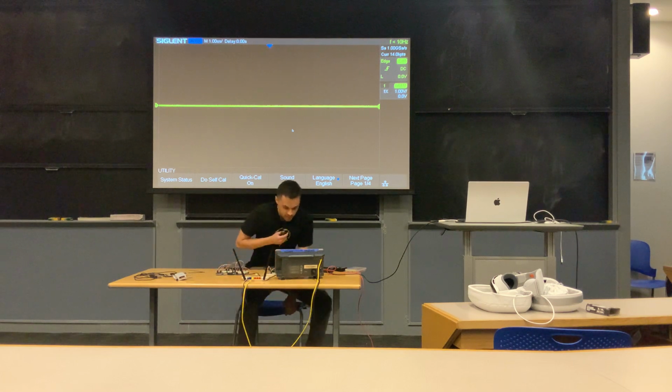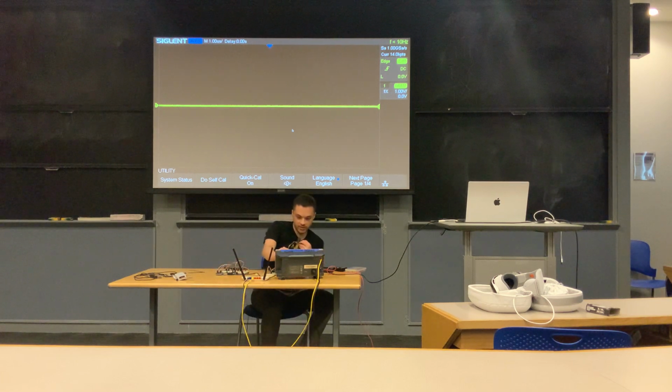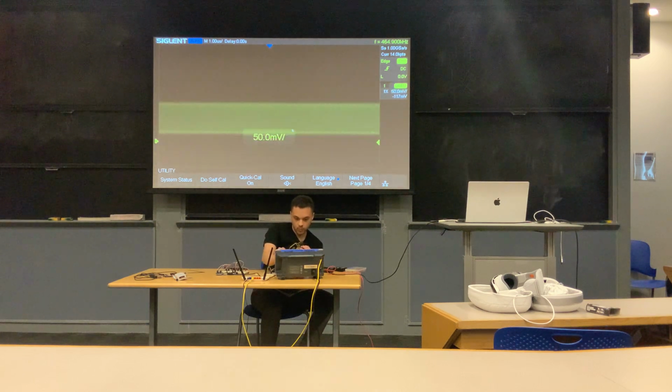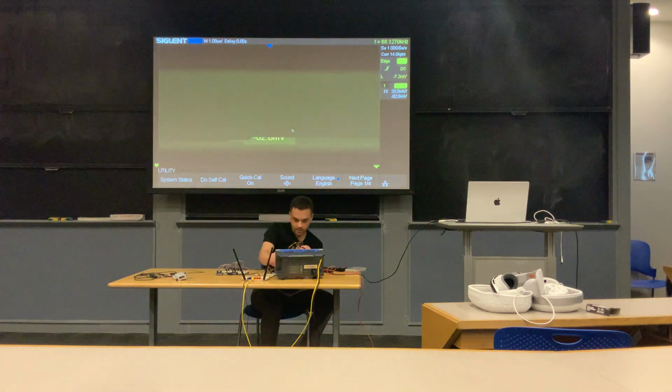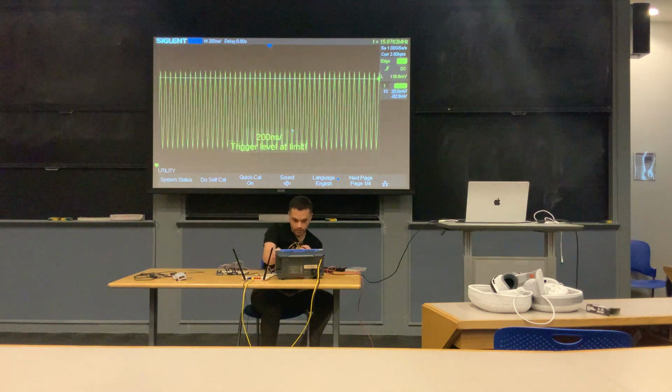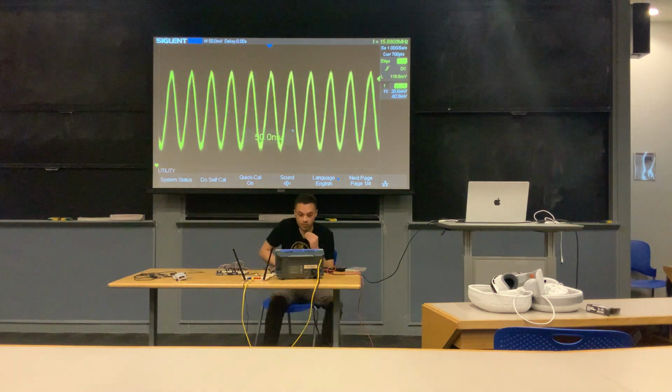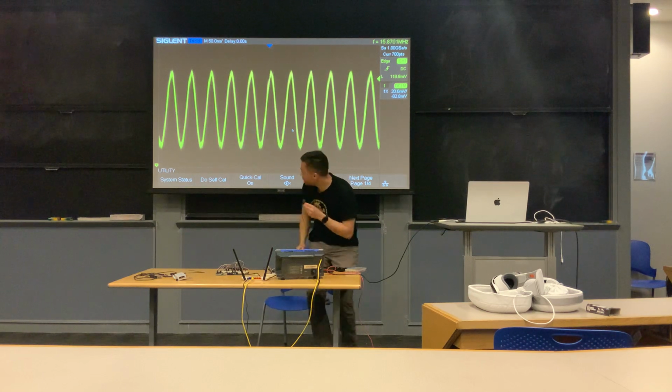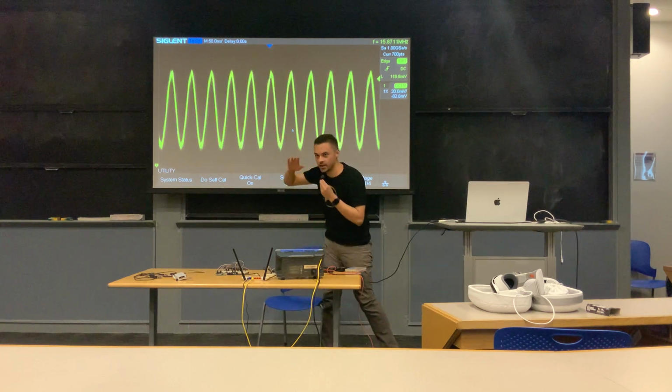So let's see if we can observe what's going on. You should be able to see there's some type of fluctuation happening. Bring this up. And we'll go ahead and set a trigger here so we can try to capture that and zoom in. And you can see we have a beautiful, stable clock. And if you look at the frequency at the top, it's roughly 16 megahertz.